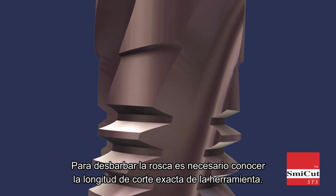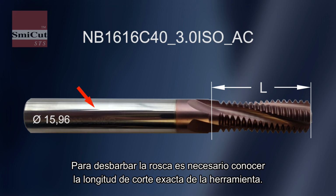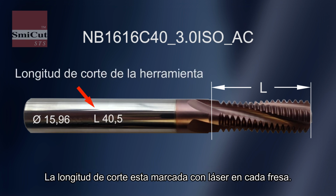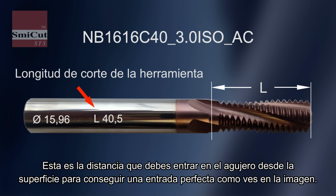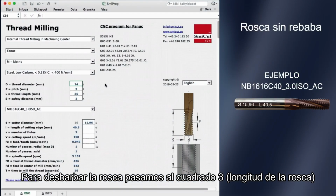To get the thread deburred, you need to know the exact cutting length of the tool, and this is laser marked on each thread mill. This is the distance you should go into the hole from the surface to get the perfect entry like you see in the picture. To get the thread deburred, we go to square 3, thread length.